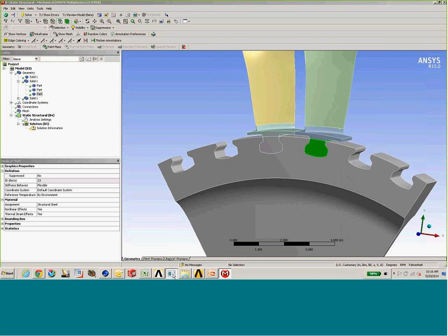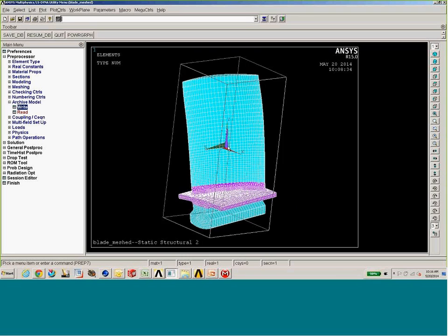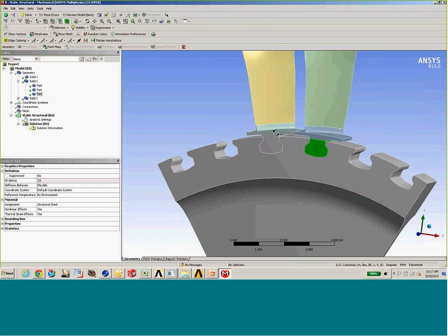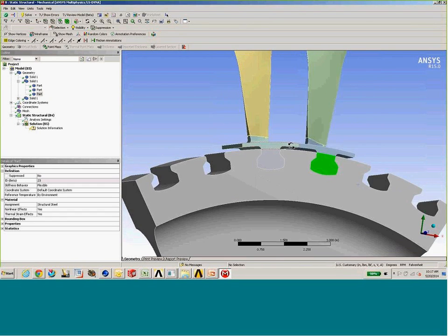Well, very simply, if we jump back to the Mechanical APDL mesh, we'll see that there are several different types of element types being used here. We're doing a hexatet transition from bricks on the blade section, bricks on the base, and then tetrahedrals and pyramids in the center. So that's enough for Ansys to realize, okay, these need to be separate bodies because they are actually separate element types in the original mesh. So that's where that comes from on the mechanical side.